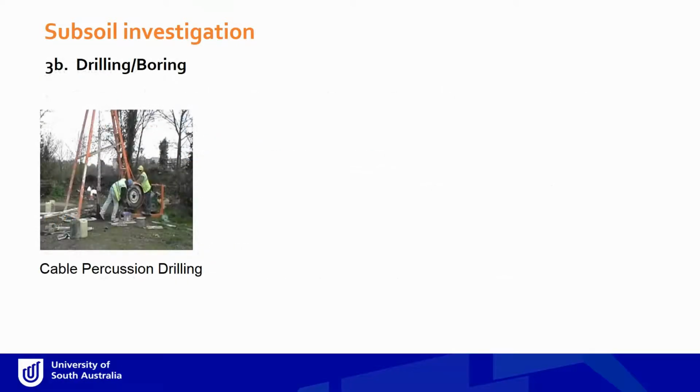Now, test pitting, even though it's a very common or easy technique, it's not applicable to all the places, because in some cases we might have to explore ground condition up to, say, 10 meter, 20 meter, extreme cases 60 or 70 meter deep. Now, we cannot obviously dig a hole that deep, so we have an alternative. We call it drilling or boring.